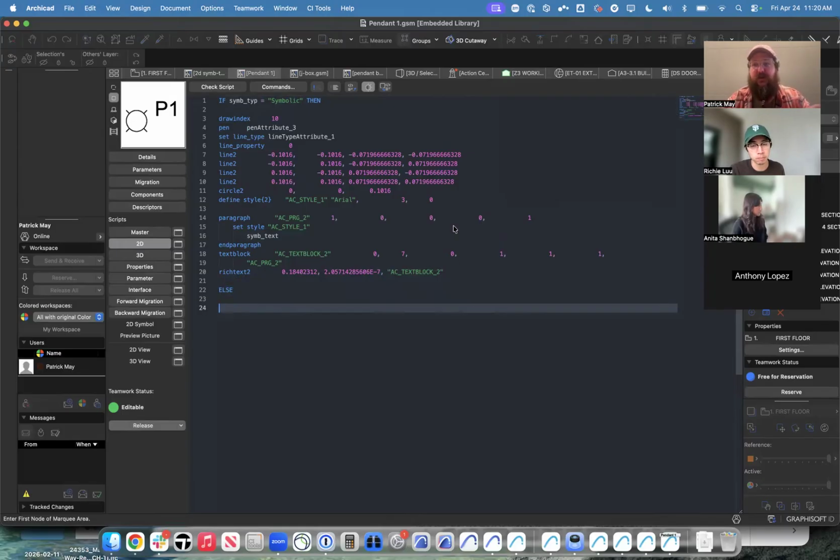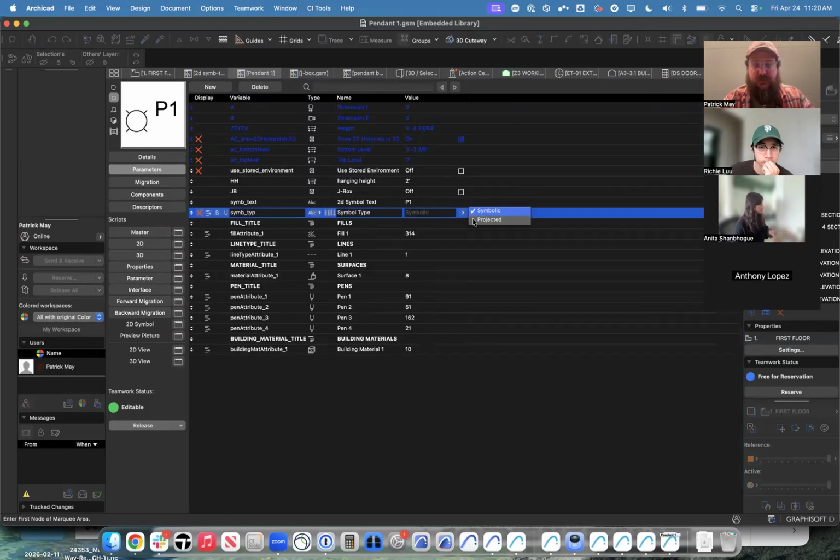And then really simply an easy way to do a 3D projection of a 2D thing, we can type the script project 2, 3, comma, 270, comma, 2. And then down at the bottom, we're going to put end if. So now I should be able to switch this to projected and see that 3D projection.